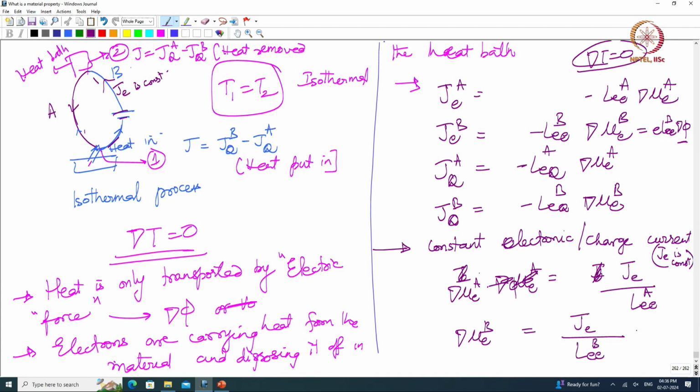So these are actually different values. The voltage drop that I will have from 1 to 2 in A across this resistor is different from the voltage drop across the B resistor, right. So it is equivalent to me having an A resistor and a B resistor. I am sending in current through these two. So the voltage drop here will be I R1 and the voltage drop here will be I R2. So that is what I have calculated here.